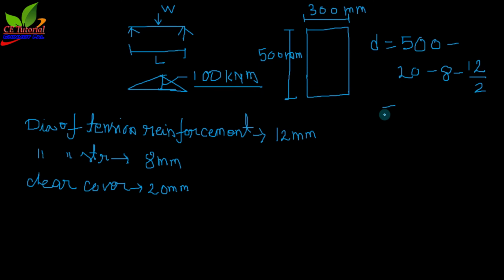Now this will be 500 minus 20 minus 8 minus 12 by 2, so 466 millimeter. This is your effective depth. So suppose this is the effective depth.